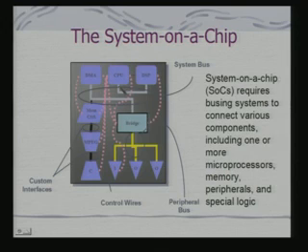In fact, if I now look at system on chip, what is a system on chip? It is actually what we have seen in terms of discrete components on a PCB being put onto a silicon element. And a system on a chip can have multiple processors as well. In fact, we have already seen OMAP, which has got an ARM as well as a C55 DSP. So, this is an example of a system on a chip.